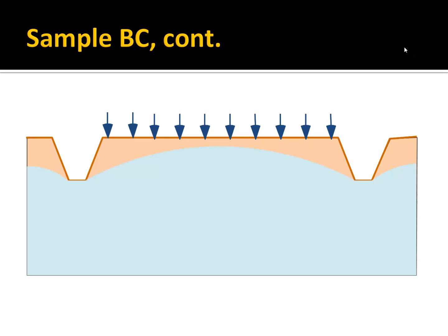So again, to solve these problems, before we start, we look at each boundary and we mark it as typically either a specified head or a specified flow. Something I didn't mention here is we have water coming in the top. That's a specified flow boundary, which is another variant of the no-flow boundary. So we have flow boundaries, we have head boundaries, and once we define those, we are able to solve our governing differential equation.